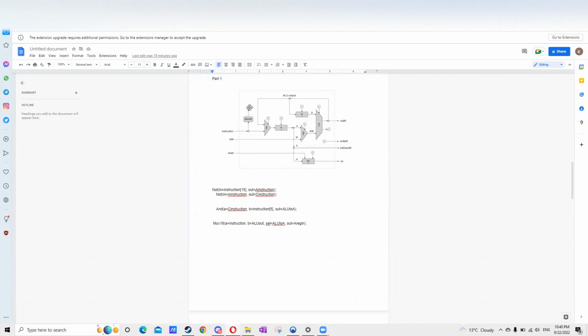So the select is the selector here. It stays there, and then you don't see the line, but it does jump to others, and then the value of the ALU output comes here, goes to the mux, and this was the select right here, ALU to A. It will decide whether it's an A or C, and then it will go to the A instruction. So see, either it's the NOT.